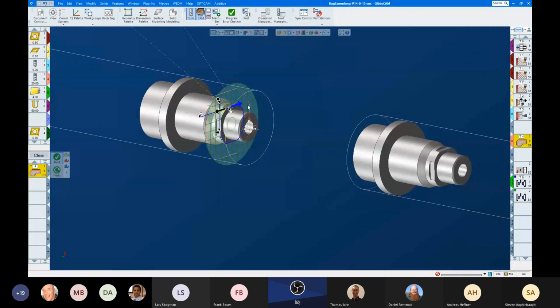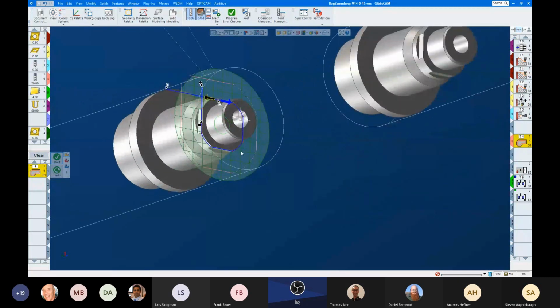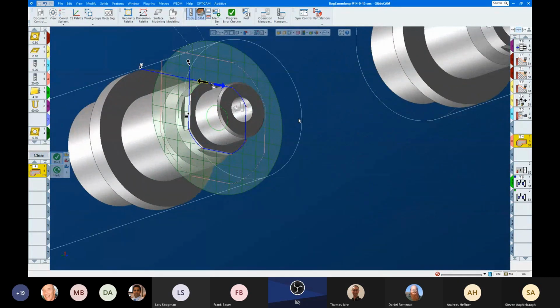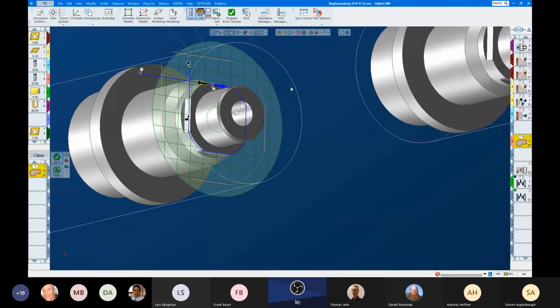If you have a look at the toolpath, currently it's without the rounded corner options, and you see the toolpath will stop immediately as soon as the edge is reached, and by this the tool will speed along. You can see rapid along the material that's already machined, and it wouldn't be too nice to have this on a machine actually. So I wanted to extend the toolpath a little bit.